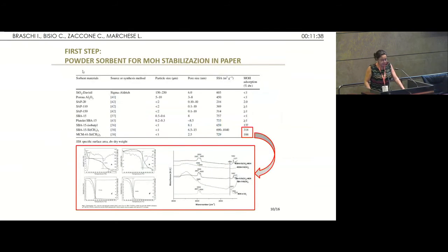So we tried different sorbent phases, and then we selected a mesoporous material, a porous silica material functionalized with an organic molecule, just to increase the affinity for mineral oil. The sorbent was stable to eventual thermal treatment for its subsequent recycling.